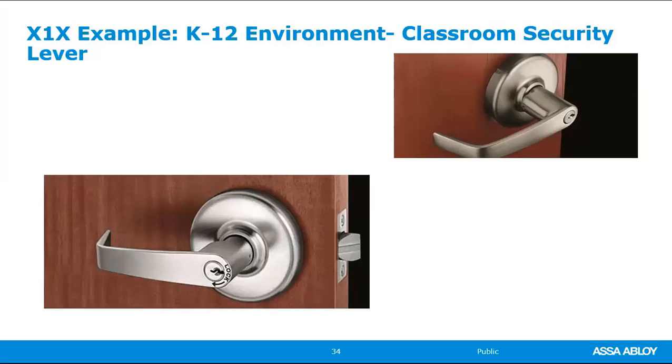Now, a classroom function lock means this. A classroom function lock does not have a key on the inside or a push button on the inside. A classroom function lock has to be locked, left unlocked, or left locked. It's binary. It's either or by use of the key from the outside. However, because classroom security needs to be increased because of school shootings and so forth, we now put the key on the inside also. Now, because of life safety, you cannot lock that inside lever down.